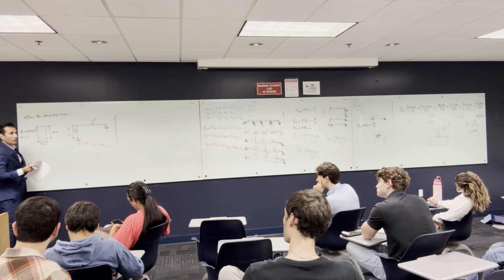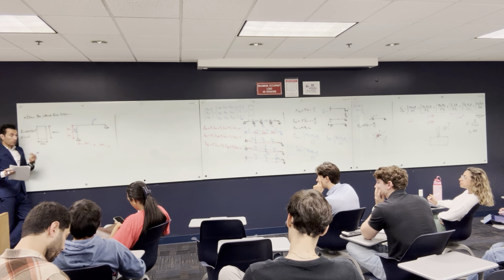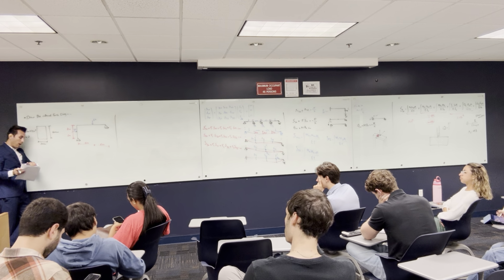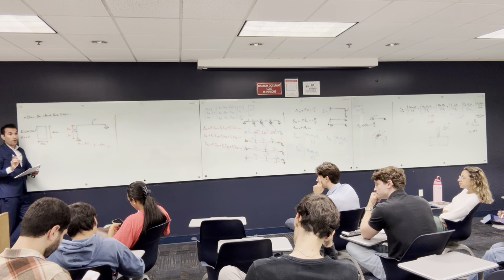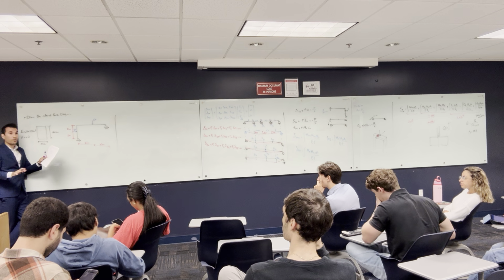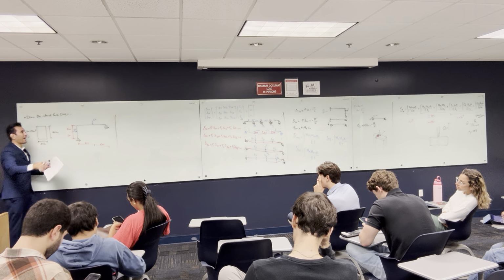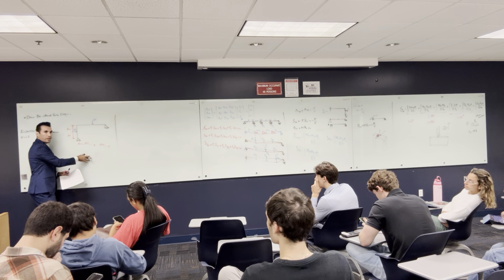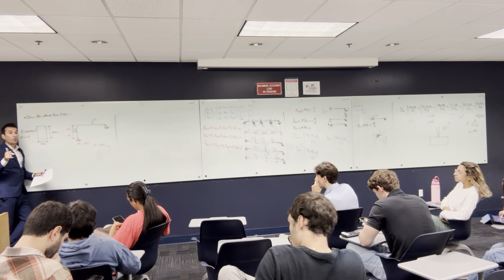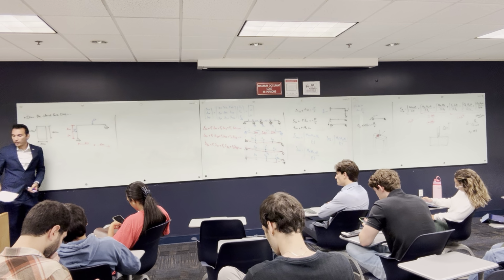All right, so I solved this problem with shear deformation, normal deformation and bending deformation. But what I'm going to do now is only solve this section for the bending deformation. You can check how I did the normal deformation here, same sequence. If I want to do it with normal, shear and moment, I have to draw the bending moment diagram, the shear force diagram and the normal force diagram, all the diagrams. But if I only do bending deformation, I only need the bending moment diagram. But let's draw the 3 of them.